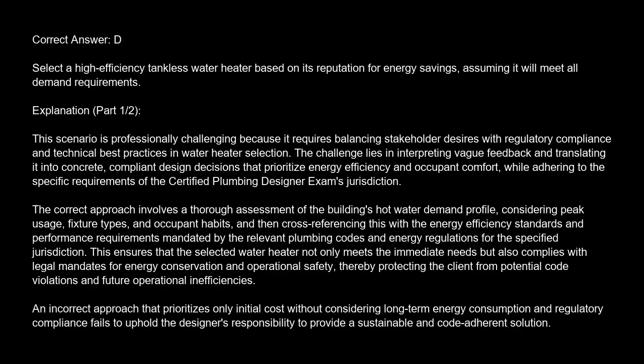The correct approach involves a thorough assessment of the building's hot water demand profile, considering peak usage, fixture types, and occupant habits, and then cross-referencing this with the energy efficiency standards and performance requirements mandated by the relevant plumbing codes and energy regulations for the specified jurisdiction. This ensures that the selected water heater not only meets the immediate needs, but also complies with legal mandates for energy conservation and operational safety, thereby protecting the client from potential code violations and future operational inefficiencies.